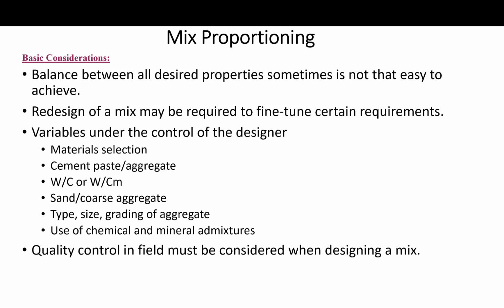Redesign of a mix may be required to fine-tune certain requirements, and that's why we have a trial batch. After a mix design, we have a trial batch to make sure the results are what we expect, and then we fine-tune the requirements.